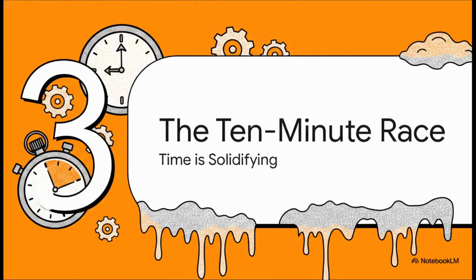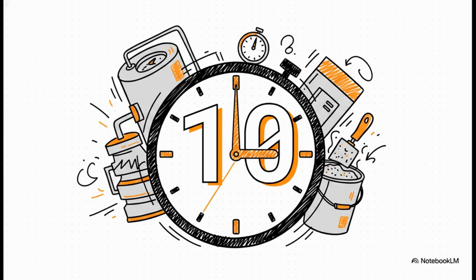All right, Section 3, the 10-minute race. Because in construction, time is quite literally solidifying. 10 minutes. That is the strict, critical time constraint mandated by the standard. From the exact moment the sample is obtained, the technician has exactly 10 minutes to complete the test for air content. And get this, that includes transportation and remixing the sample. It injects this crazy ticking clock urgency into the whole procedure.